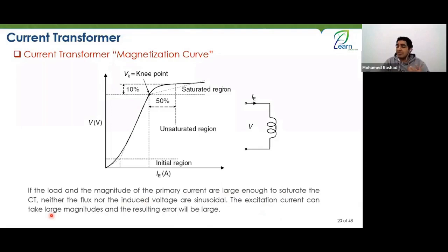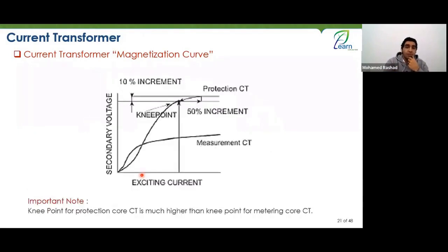This is what I explained to you when I told you the reason why there is a ratio error, meaning why the 1000 amperes are not converted to 1, why there is always an error. There is always an error, because part of this flux is used in the magnetization process of the iron core to align the dipoles. That's why during manufacturing, they don't make the CT exactly 1-to-1. Instead, they might add a turn to compensate for this error. All right, guys, that's great.